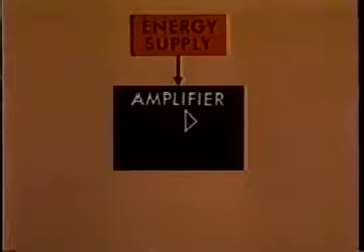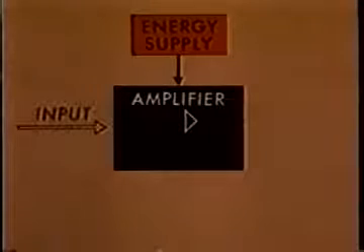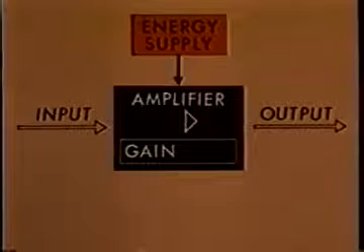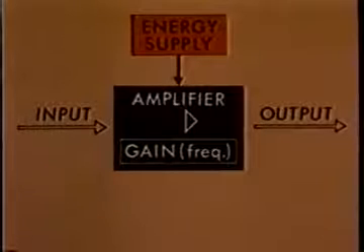We can picture the mechanism of flow instability as a frequency-selective amplifier and picture it as a black box, although this is really oversimplified. An amplifier needs an energy supply. This amplifier takes its energy from the airstream. The amplifier input is any disturbance that happens to come along. This could be upstream turbulence, noise, or an intentional disturbance we put in. The output is damped or amplified waves. When the amplification ratio, the gain, exceeds unity, we have instability. The amplifier gain varies with frequency and also depends upon flow parameters.